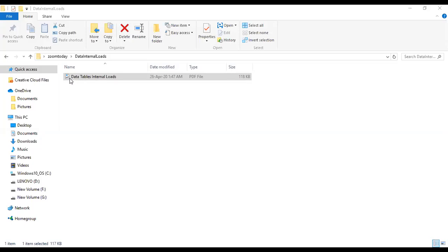Now a school, of course, you don't know how many students are registered, or how many students are present today or the day when you are calculating. It is not required. You should know the total area of classrooms divided by 2.5, and you will know the number of students. So you have to assume this number of students. Students may be less, students may be more, but this is the standard 2.5 meters square per occupant.